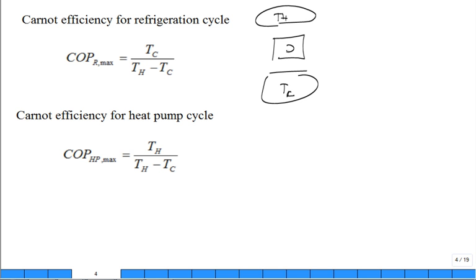And what you have is a system operating in a cycle, continuously bringing in Q sub H. Whoops, this is for refrigeration. We're bringing in Q sub L and dumping off Q sub H, having to feed it the work. That's how a refrigeration or heat pump system works. And so for the coefficient of performance for a refrigeration system, it's what you desire, a large amount of cooling, divided by what it costs, hopefully minimum work input.